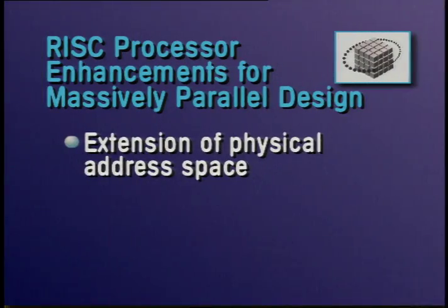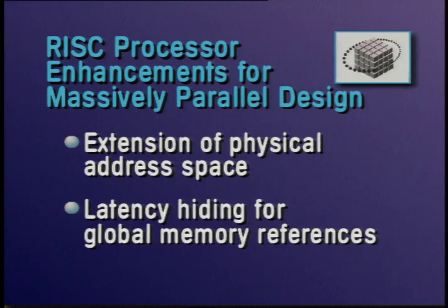Typical microprocessors can support only a very limited number of outstanding memory loads, often only one. But in a distributed memory MPP, any global reference, even nearest neighbor, which stalls the processor, will seriously affect computational efficiency. Logic must be added to support and mask many outstanding references, thereby hiding latency. This provides capability to fully exploit modern compilers that are able to accurately judge when to prefetch streams of data.